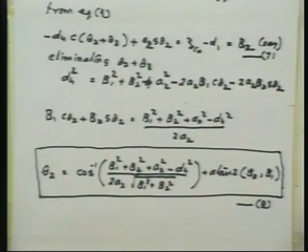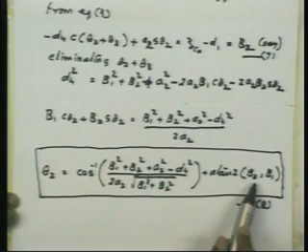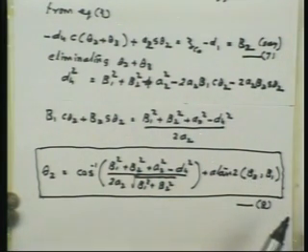Again, let us inquire about solvability in this particular case, number of solutions. This second angle, A tan 2, is fully obtained, b2 and b1 are known numerically, so you can get it uniquely. What about this? The same problem with the argument being outside the allowed range could be there. So this could be more than 1 in magnitude, in which case there is no solution here. If it is less than 1 in magnitude, there are 2 solutions. If it is equal to 1 in magnitude, there is 1 solution. These are the various ways in which solution occurs, right?